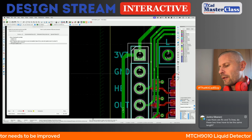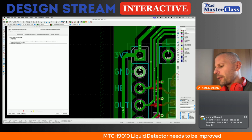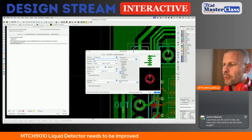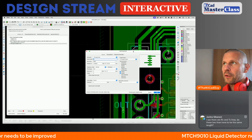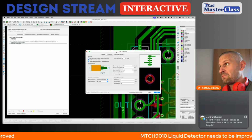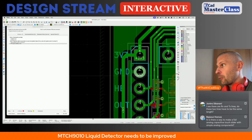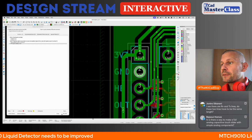Okay. There are two options. You can change the board setup to allowing one spoke only, or to change the pad connection to solid, as I'm going now. Perfect.